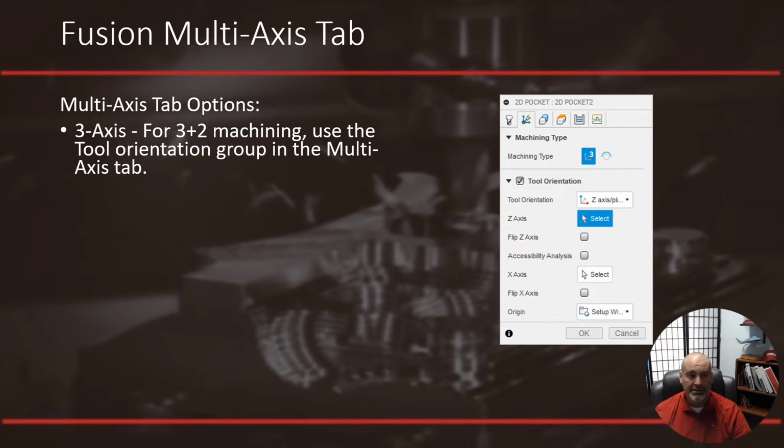It supports 4 different types of machining. Our default on most of them is called 3-axis. That's used for 3+2 machining. Use the tool orientation group in the Multi-Axis tab to set the orientation you want to index the part before applying the rest of the toolpath. So it's a little checkbox that says tool orientation, and you check that, and the options shown on the screen appear.